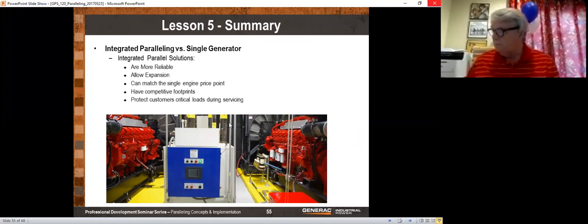All right, there's another question here about whether generator paralleling would affect maintenance scheduling. I'm guessing they're referring to how often you schedule. Oh, okay. In terms of how often you schedule, it's pretty much the same. Regardless of the size of your generator, we typically recommend maintaining a generator every 6 months.